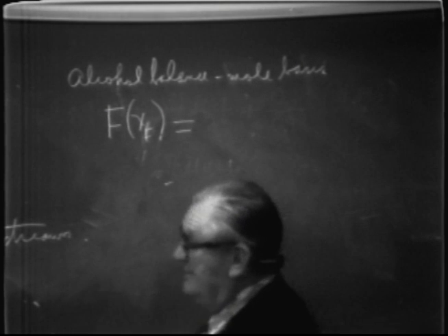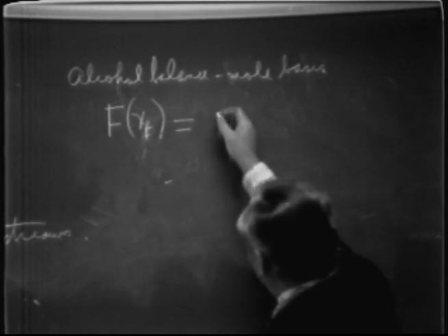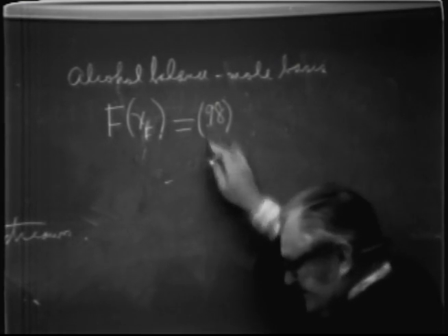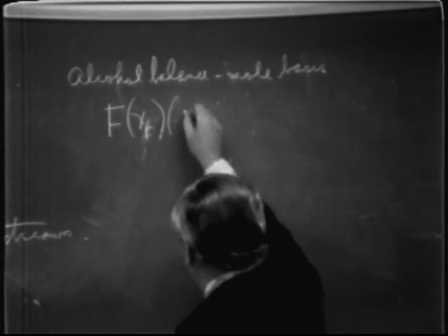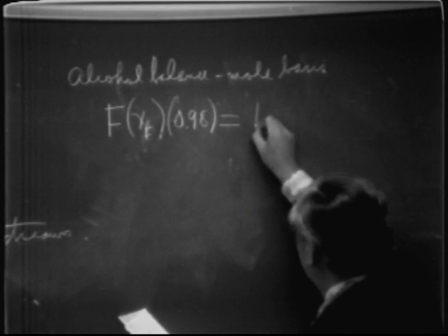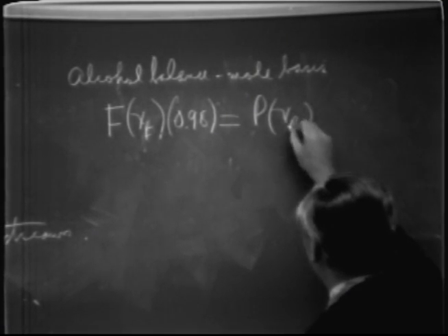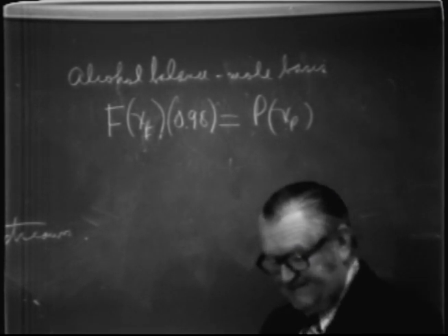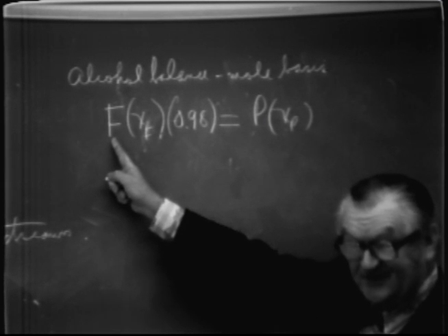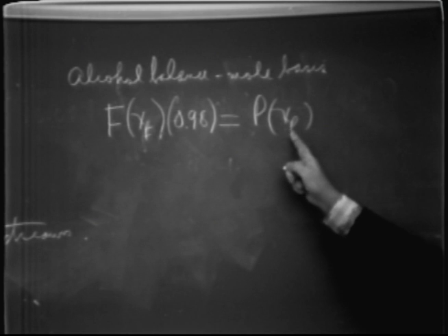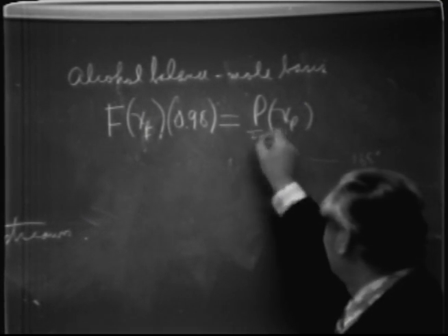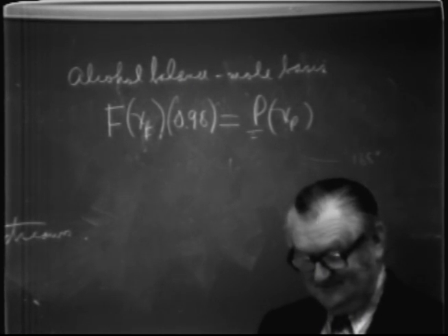In this case, we don't know anything about the bottom product. Nothing was stated about it, but we do know that 98% of this alcohol was recovered in the distillate, so we can write 98% of that is recovered in the product, P times X sub P. If we've made the proper conversions, and this 168 proof has to be converted to the proper mole percentage, then all you have to do is solve for P. And that'd be the answer.